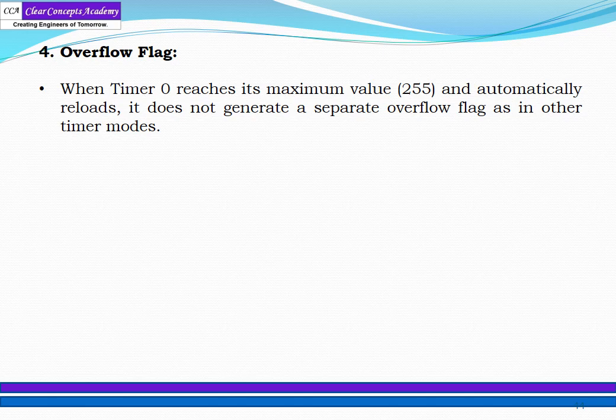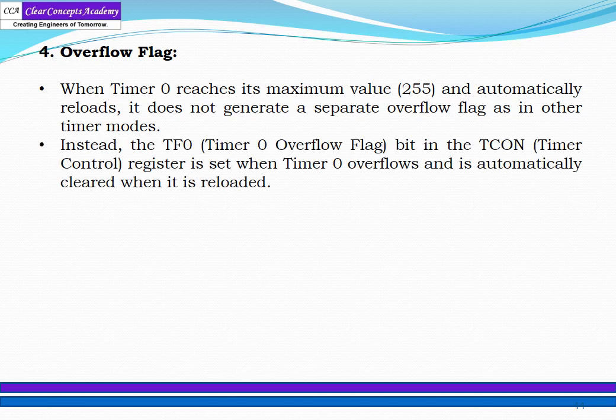Now overflow and flag. When timer 0 reaches its maximum value, that is 255, and automatically reloads, it does not generate a separate overflow flag as in other timer modes. There is no other flag, because you only have to store the value in TH0. Instead, the TF0 timer 0 flag in the TCON timer control register is set when timer 0 overflows and is automatically cleared when it is reloaded.